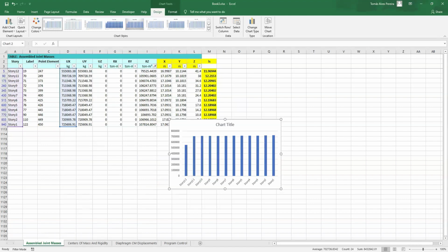There is another topic I forgot to mention when we looked at the height stiffness table. There are small differences, specifically at the roof, where we see a slight increase in story stiffness because we have a perimeter beam that wasn't present on other floors. While this is true, one must apply engineering judgment to ensure we aren't looking at stiffness changes with millimeter precision. These are qualitative values that can be observed and verified quantitatively, but engineering judgment means we shouldn't just look at numbers and seek exact limits to satisfy. We simply look at the behavior of both mass and stiffness criteria and remain satisfied with results that appear reasonable. This is the case for this building's regularity in height.